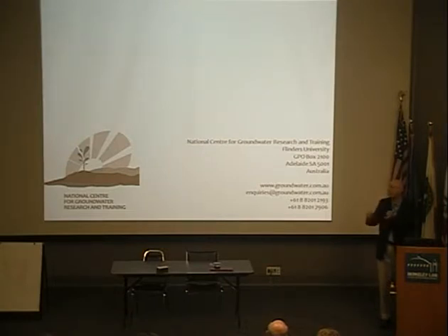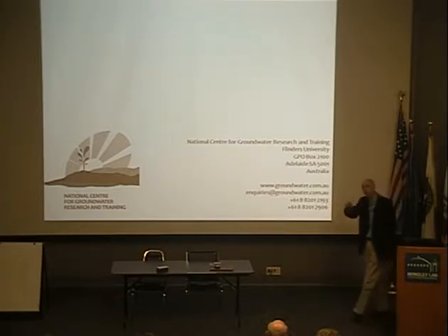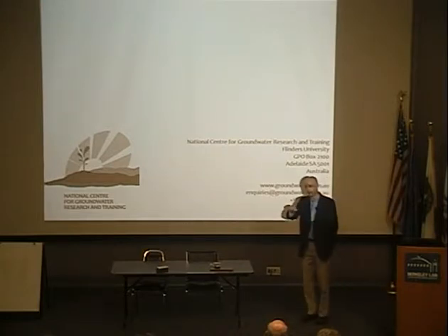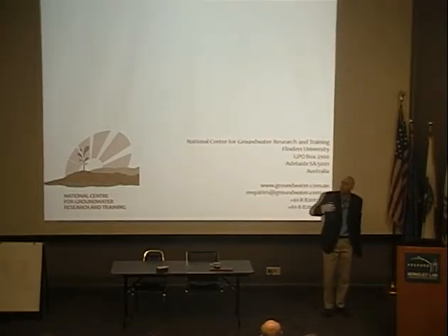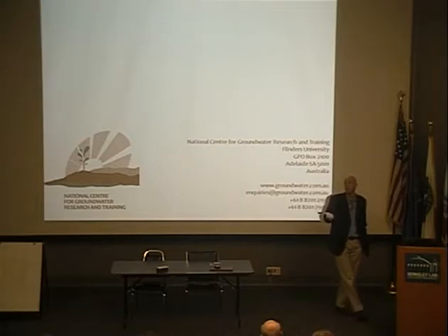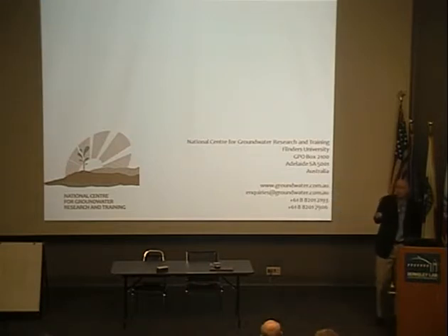We've done some work that I didn't describe looking at hyporheic zone residence times by measuring radon within the sediments. Essentially the radon concentration within the sediments can tell you the residence time of water within the sediments. So we've tried to correct for it. But it's an issue with all of these methods, and the temperature particularly has been modelled as one directional flow. And if there's hyporheic exchange, the upper layers aren't like that, so it is a complication.